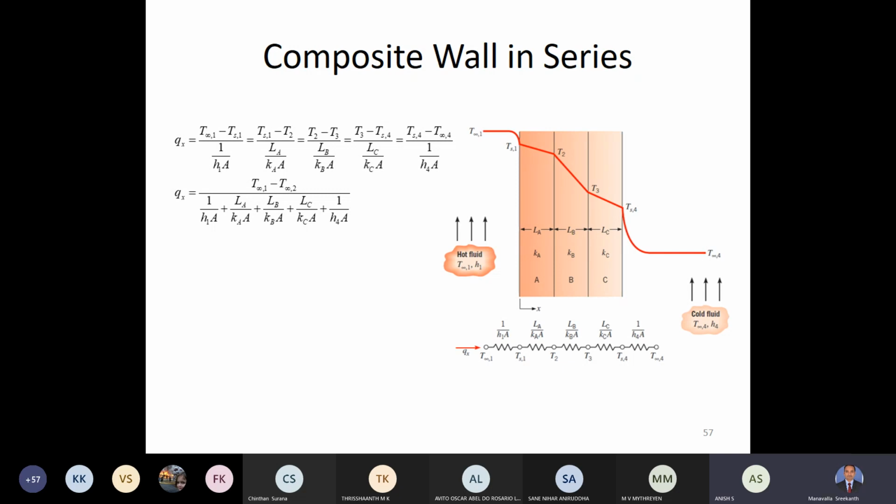In pipes connected in series, the amount of fluid flowing in the first pipe is the same as the amount of fluid flowing in the last pipe. That means the flow rate is the same, but the pressure drop in different pipes will be different depending on the diameter, length, and surface finish of the pipe.